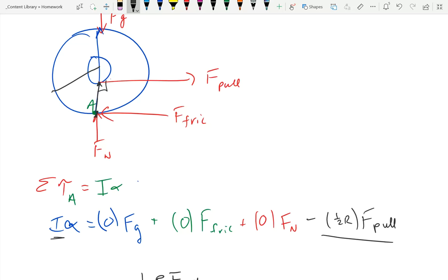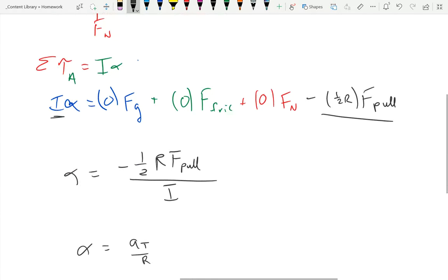If it's rolling to the right, what direction do you get for the angular velocity? Is it clockwise or counterclockwise? Clockwise, so negative, right. Or you can take your right hand rule, wrap your fingers the way it's rotating, your thumb points in, so negative. So a positive acceleration corresponds with a negative angular acceleration for our definition of directions here. And so I got a minus sign here.